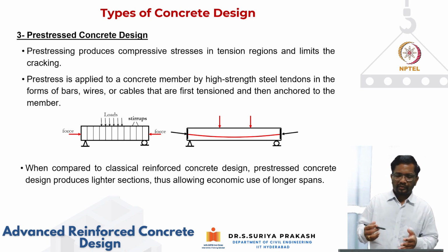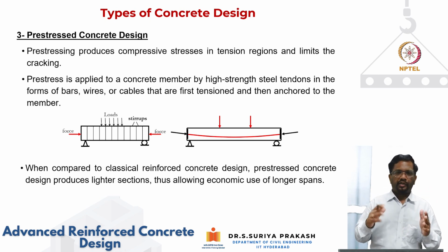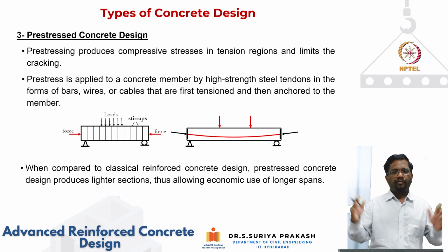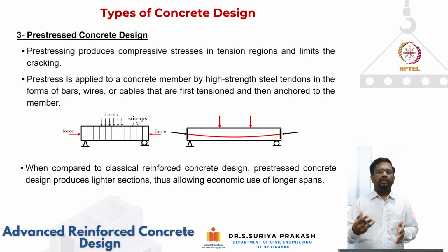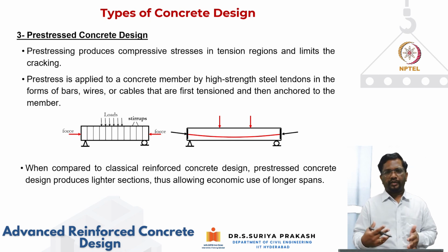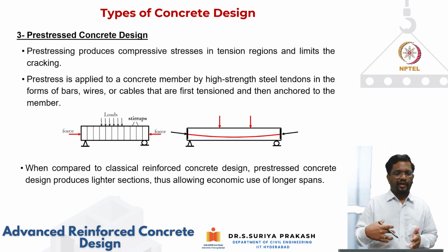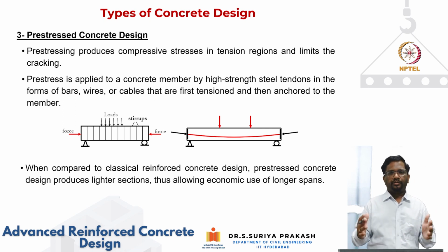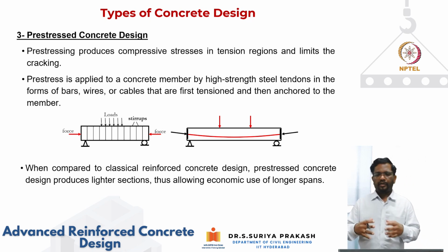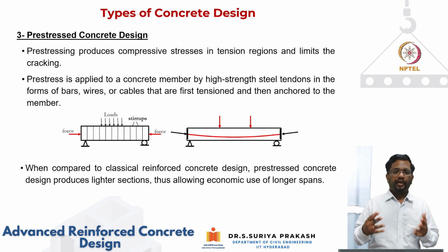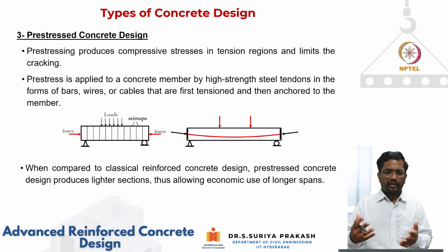What we really do here is we put the concrete in compression even before any external loads are applied, and we apply some pre-compression in the regions where tension is going to develop due to external loads. In this way, we can increase the load capacity at which it is going to crack. Because wherever tension is going to develop, I have put some compression before, that compression has to be nullified and it should reach the modulus of rupture before it cracks. So you generate a nearly crack-free structural element under service loads.